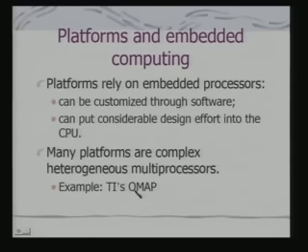An example is TI's OMAP, which we had already discussed, which has got ARM 9 as well as a DSP processor sitting inside. The behavior of these will be determined by mapping software onto those two processors, and that would give me a particular instance suiting my application.